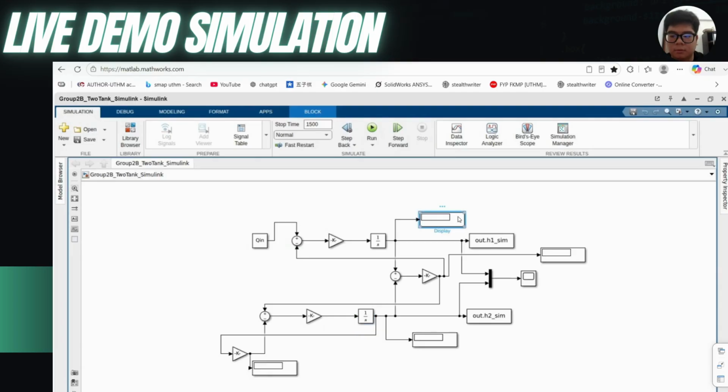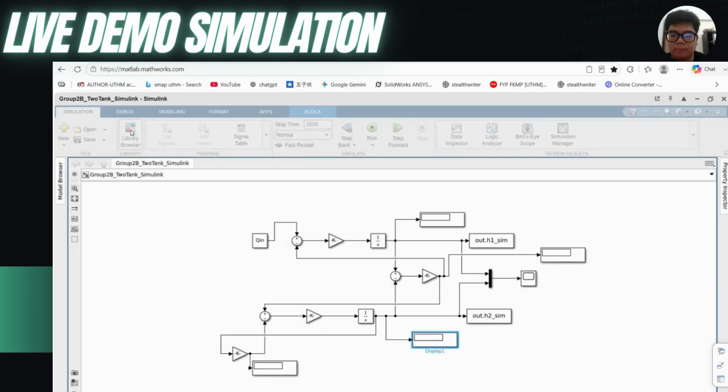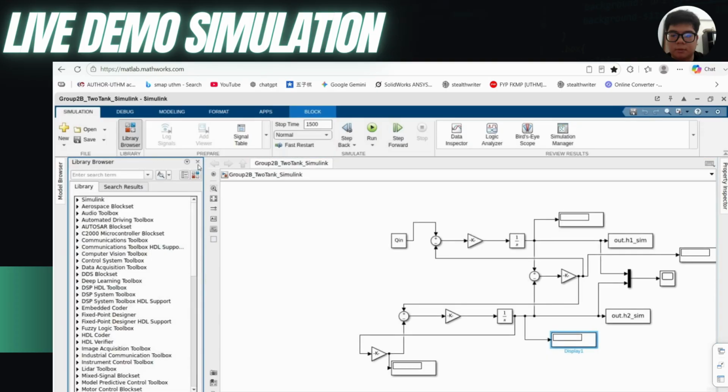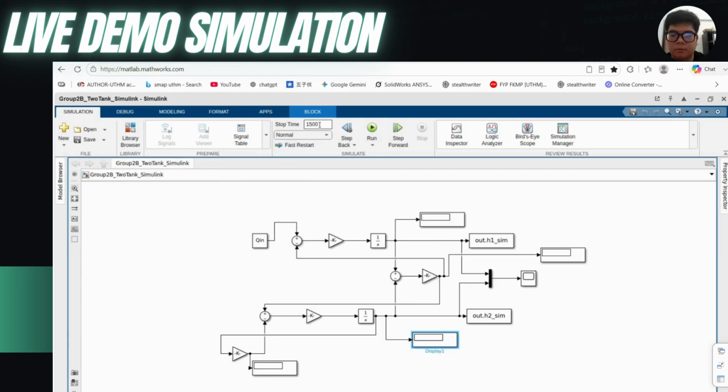This is the display for the water level of H1, and this is for H2. The products all come from this library. The end time step I set is 1500. So now we run the simulation. We can see the output of H1 is 2.5 and the output of H2 is 1.5, which matches the theoretical value.